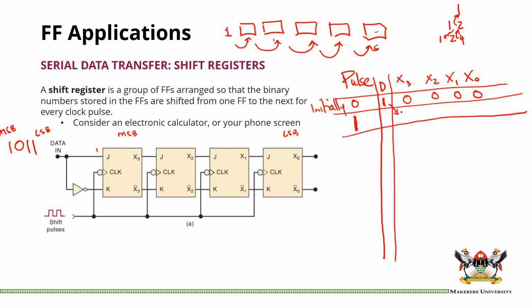That is why we say shift. That's why we call these shift registers. So this will be shifted here. And this 0, which was in X3, will be pushed into X2, because remember, X3 being 0 is here on this line. So if we clock, this 0 comes there. So this 0 will be pushed here, that 0 will be pushed here, and the 0 in X1 will be pushed into X0. Now the 0 in X0 is basically discarded. It might go into some other part of the circuit, but here, because of the circuit, our circuit ends here. That's why we say discarded.